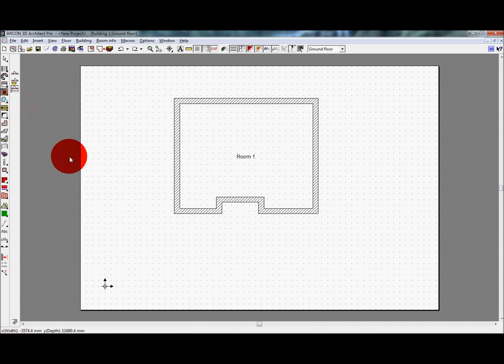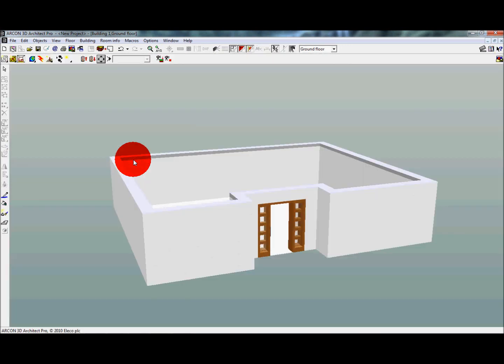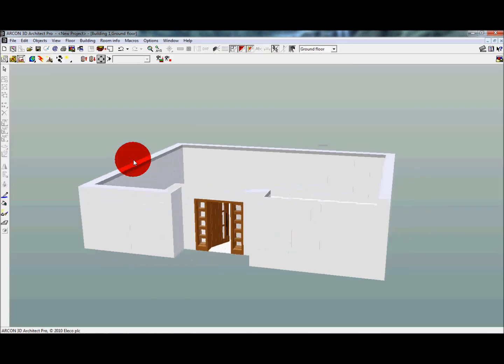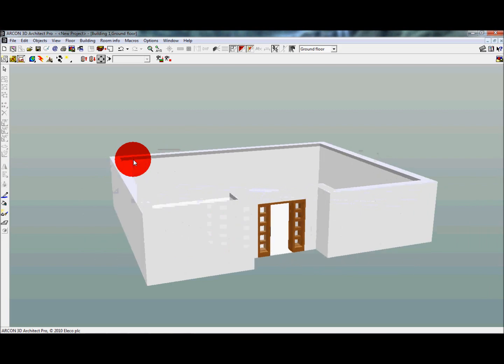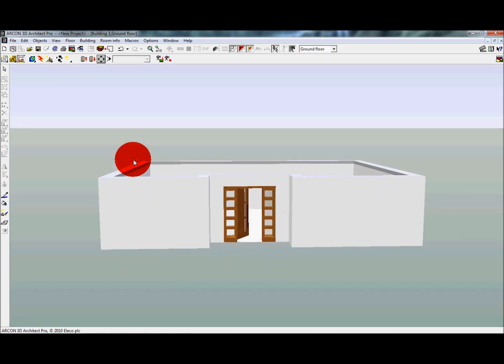The final placement option enables you to add a door at the middle of 2 points. We left-click on each of the 2 points in turn and the door will be placed exactly in the middle of these 2 points. We can of course enter the 3D view at any time by pressing F12 to view the progress we have made so far in the 3D model. Press F12 again to toggle back to our plan.